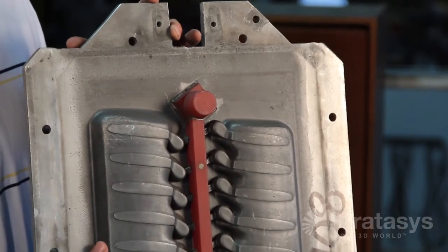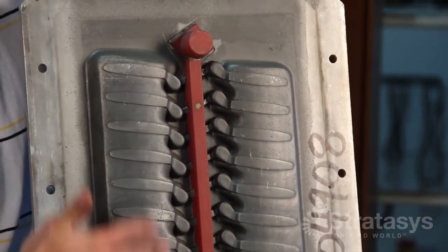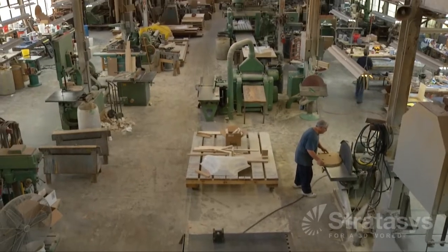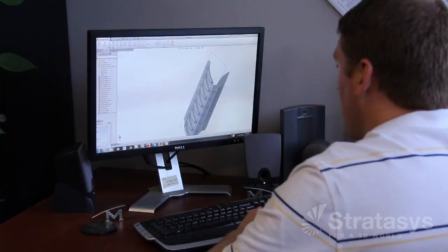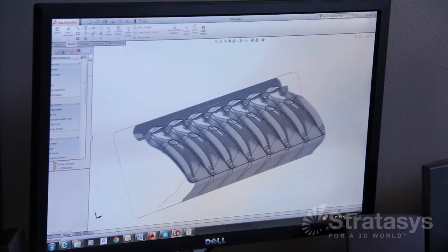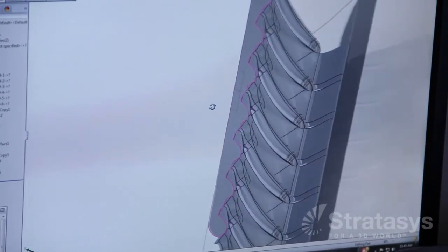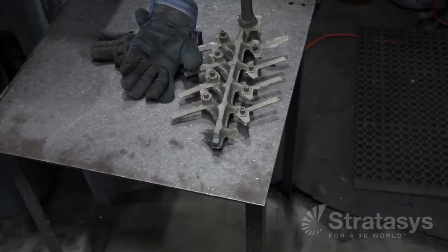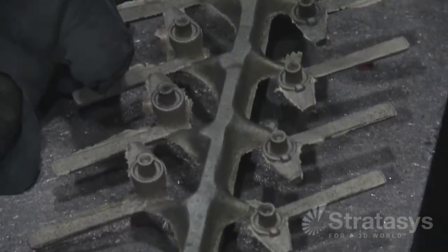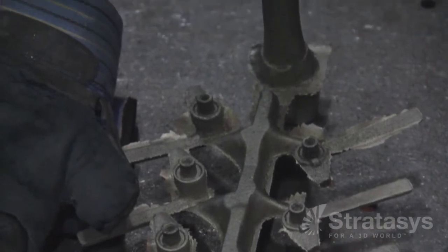Traditionally, skilled pattern makers in woodworking or metal shops created sandcasting patterns. As the availability of pattern shops has declined, innovative and efficient options such as FDM have filled the void. Complex patterns that once took several weeks to make are now produced in-house in only a few hours on an FDM system.